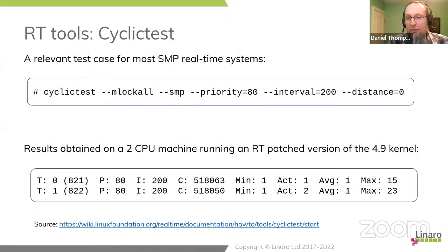So it's a statistical approximation, a bit like profilers, of what you can actually see as your worst cases. But the fantastic thing about it is it measures some of the unmeasurables. It measures the firmware cost of waking up. And this is one of the reasons the RT guys really like this as a tool for PC-like platforms where you have a closed source BIOS that can be doing all sorts of strange things when you make calls into EFI or you manipulate the system in some way.